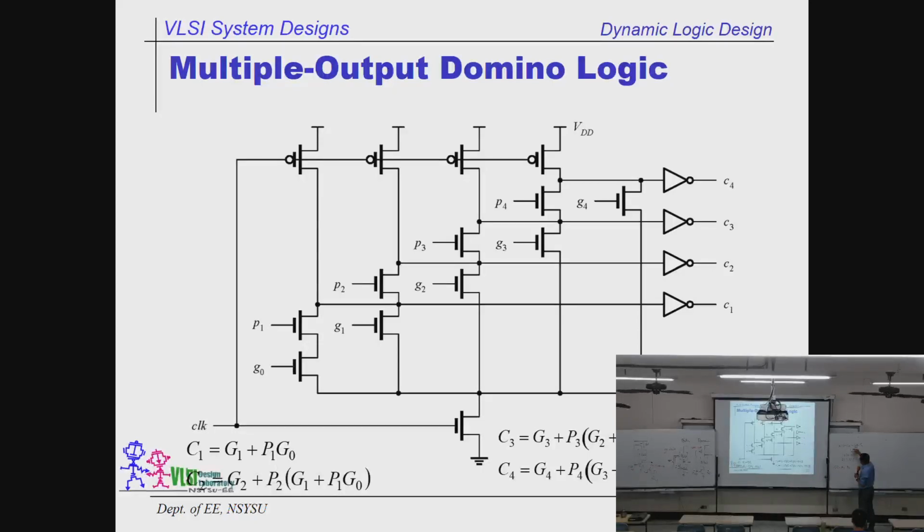If this is 0 plus 0, we are going to have a 0 to move forward. So we are going to have a pass, propagate, if exactly one of them is 1, exclusive. Is that clear? Okay? So we guarantee that if both of them are high, we are going to generate 1. And if one of them is high and the other one is 0, we are going to pass the carry.